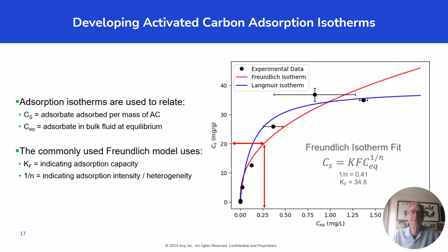The results of the analysis are plotted on a log scale: milligram of contaminant absorbed per gram of carbon by final desired concentration. The curve can be fitted using either a Freundlich or Langmuir isotherm. Freundlich is used due to the abundance of statistical tools available. Based on our desired final concentration in the solution, we can see the amount of contaminant absorbed per gram of activated carbon.